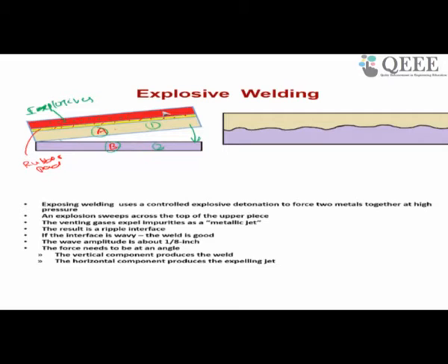So what will happen? Whatever oxide layer will be there in the bottom part and in the top part interface, because of this heat, it will explode. It will go out from the material. So there is like a jet. It will form like a jet, and it will come out. Those oxide layers will come out because of this velocity, out of the workpiece material. And these two fresh pieces will be joined together within very short time.